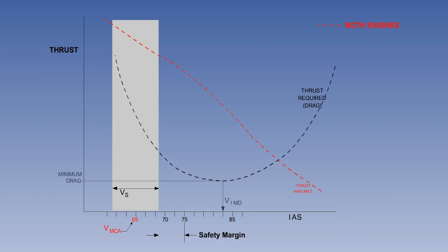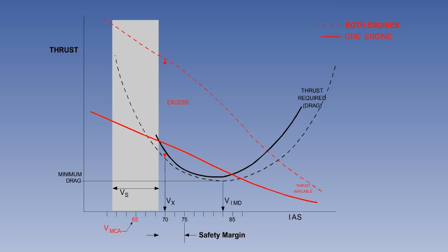You learned in the earlier flight mechanics lesson on climbing that an aircraft's ability to climb depends on the excess thrust available after aerodynamic drag is balanced. If a twin-engine aircraft loses an engine, thrust is reduced by 50%. But excess thrust, that is, thrust minus aerodynamic drag, is reduced by more than 50%, as shown in the graph on the screen. The ability to climb may be reduced by as much as 80%.